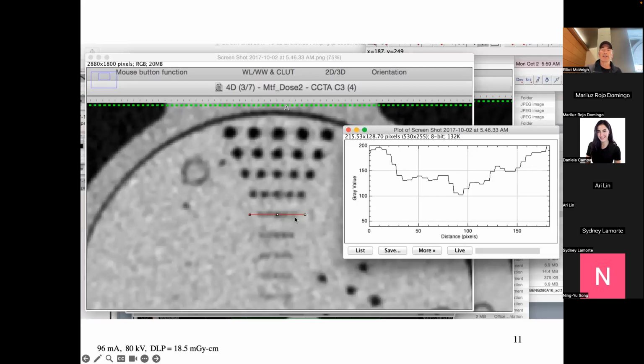And then when I look at that modulation for the image that was obtained with many fewer photons, like perhaps a factor of 20, then what happens is smoothing is done in order to decrease the noise in the image, which essentially smooths out these details at this frequency. And so now we see this plot, right? And you've essentially wiped out that frequency. So the MTF has now moved in towards zero frequency.